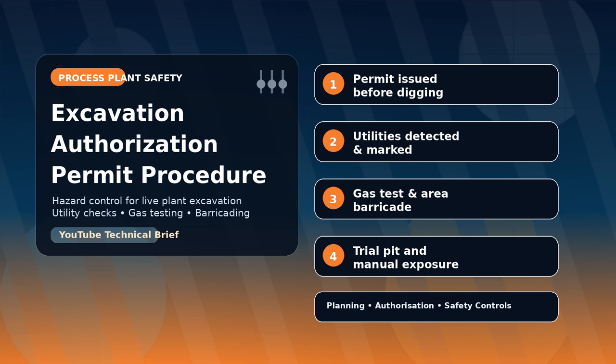As there are underground utilities, you may be allowed to do only manual excavation, where you use only the shovel. Then you also need to confirm whether any other utilities are passing over that location. So you may need to do a topographic survey and some ground scanning. There are many ground scanning techniques, like ground penetrating radar, or an electromagnetic cable locator. In one of our previous projects, we used an electromagnetic locator.